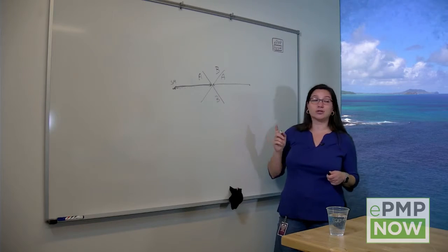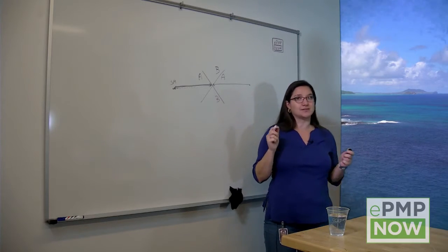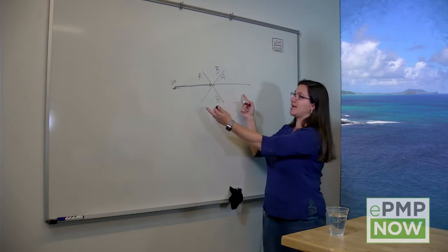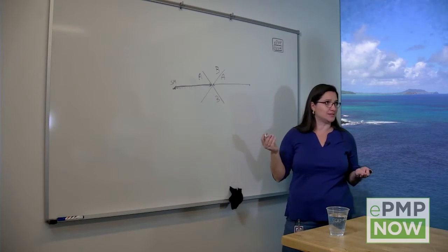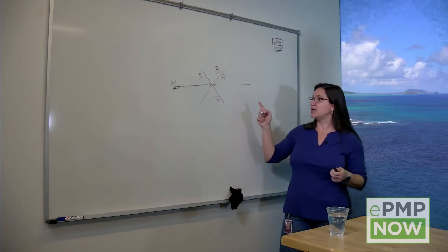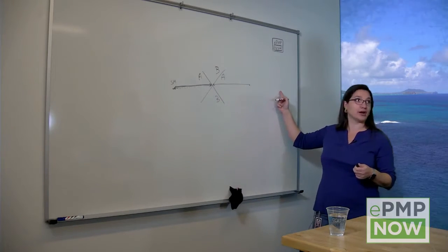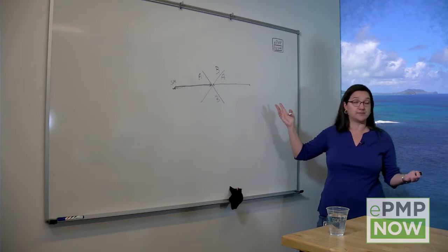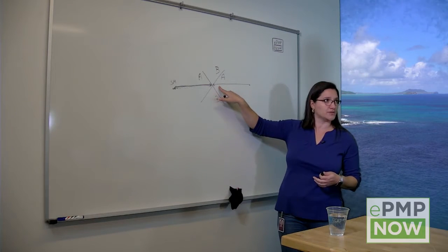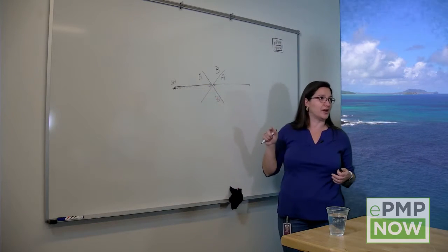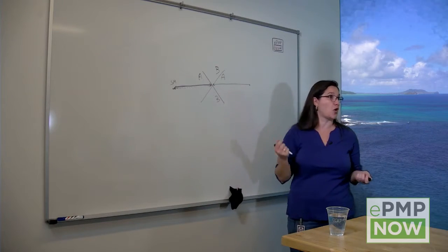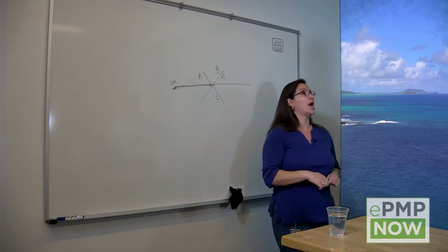Again, the attenuation is provided by the front to back ratio. Now here, another consideration is the relative distance of the 2 subscribers from the tower. If the 2 SMs happen to be exactly the same distance, then the only attenuation is provided by the front to back ratio. If this subscriber happens to be farther out, the distance helps. There is additional attenuation. But if this subscriber happens to be really close, now the protection provided by the front to back is reduced because this signal will arrive even stronger, and it becomes more important that front to back is high. Absolutely. In that case, absolutely.